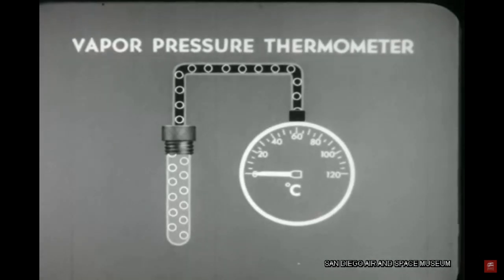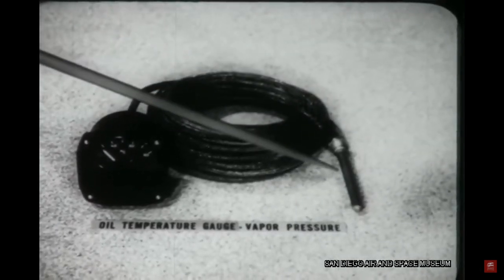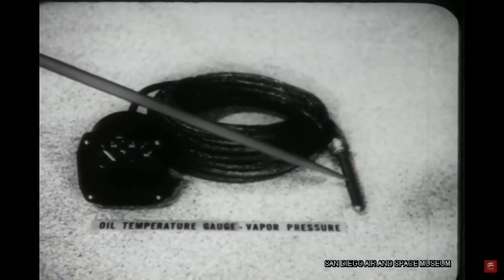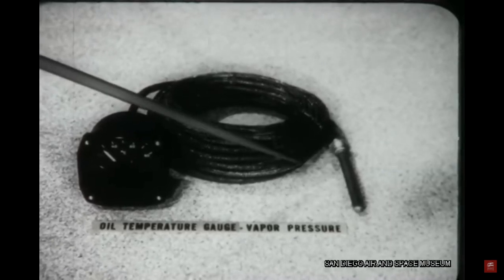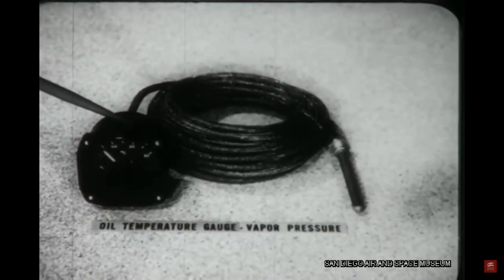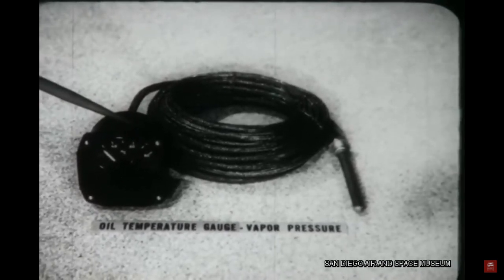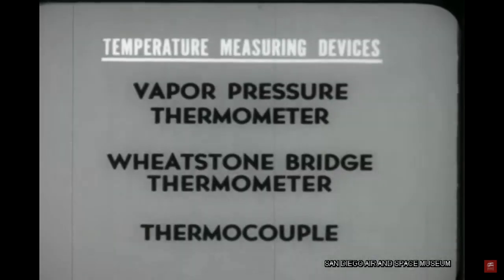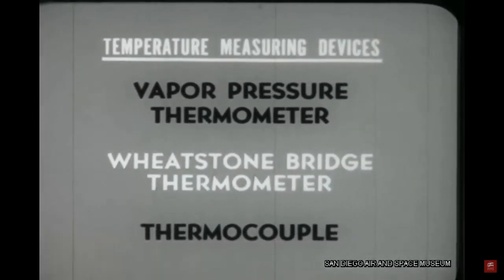The vapor pressure principle is used in oil temperature gauges. Here we see the bulb which is inserted in the oil system, the tubing and the instrument containing the Bourdon tube, and its mechanical linkage. Oil temperature gauges may also use another of our 3 devices. The Wheatstone bridge thermometer is an electrical device.